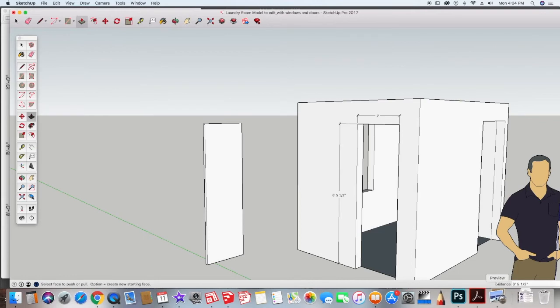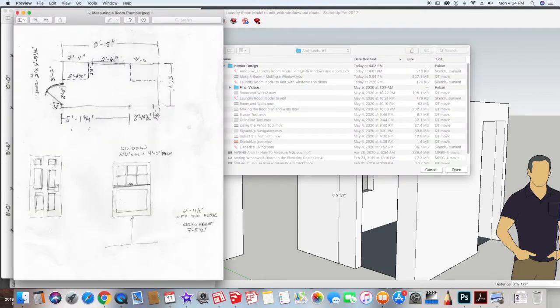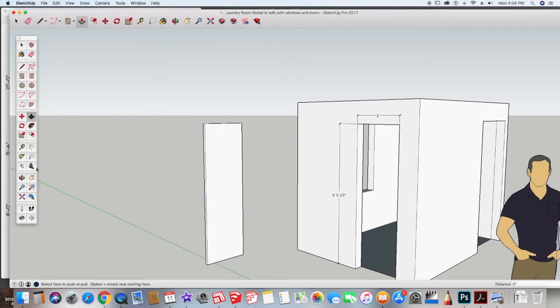This door is a little complicated. I didn't really sketch this to a proportion, but basically there's 4 little panels in the door, and that's surrounded by, again, the stiles and the rails. The rails are the parts that are horizontal and the parts that are vertical are the stiles. And so I need to make up some numbers which will make that look good. So I've decided that I'm going to offset the outer side 4.5 inches. I'm going to click the offset tool and I'm going to go in 4 and space 1/2 inch.